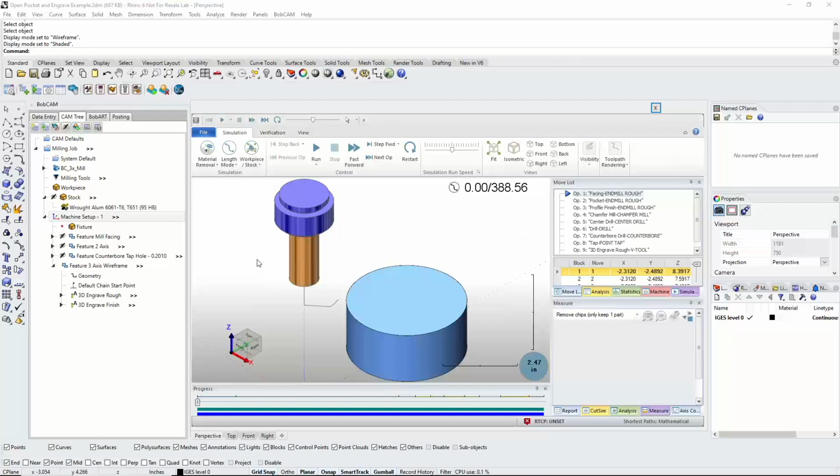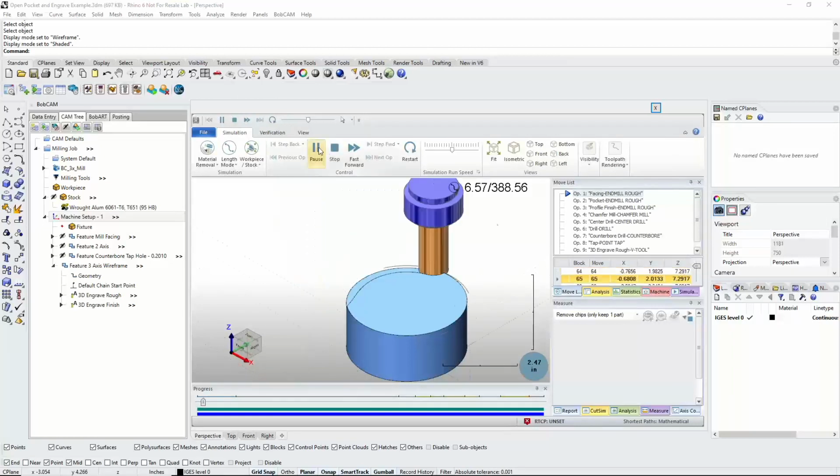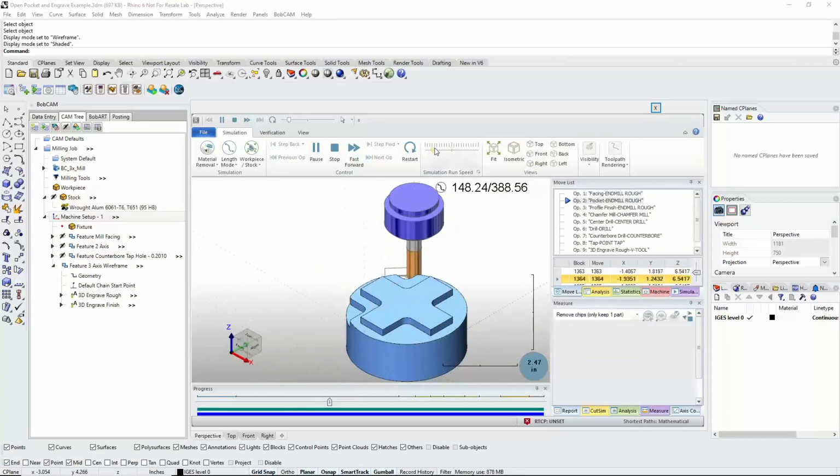All right. So now that the simulation loads up, we'll go ahead and say run. And it's not too fast. So there we go. We'll do that in 1 pass. And then we got our 1/4 inch passes. And this is that advanced pocket. So it's going to shave as much of it out as it can until it can do a full pass.